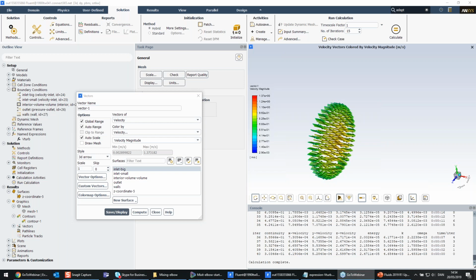Okay. So I don't see any more questions. Yes, there's another question here. Can the VOF-to-DPM model go both ways, from discrete particles to VOF depending on the volume fraction? For the first release, it couldn't, but I'm quite sure with the new release that's coming that you're able to do that as well.